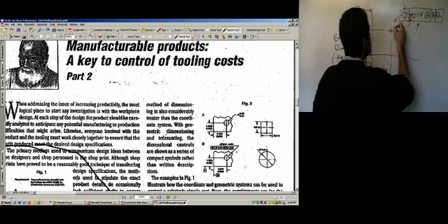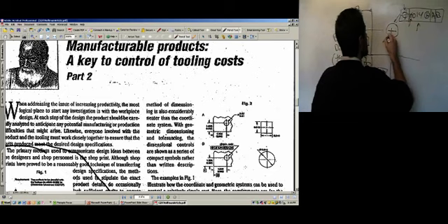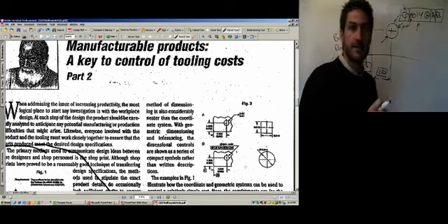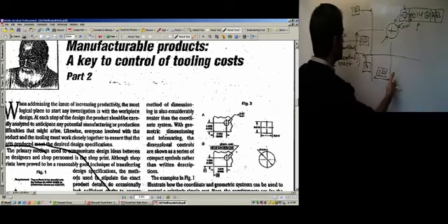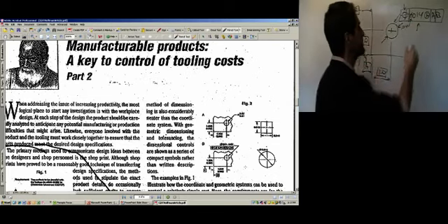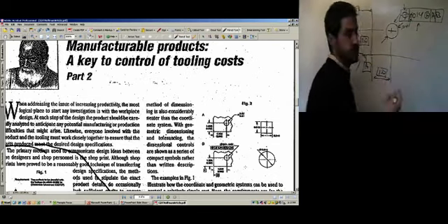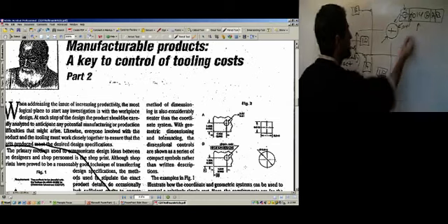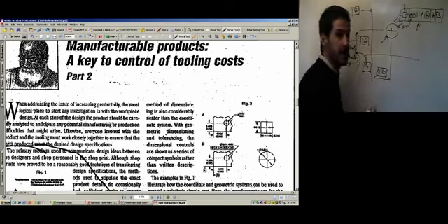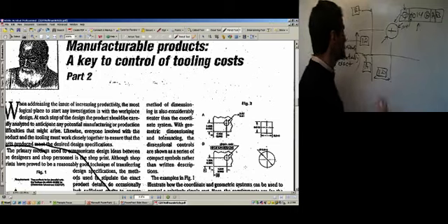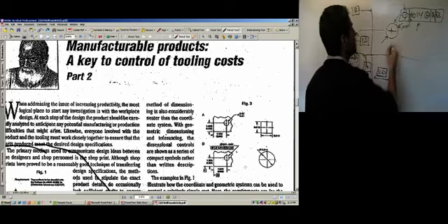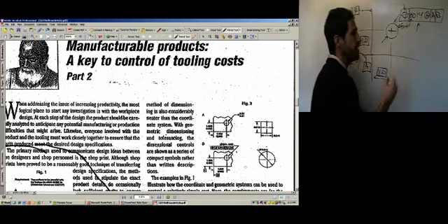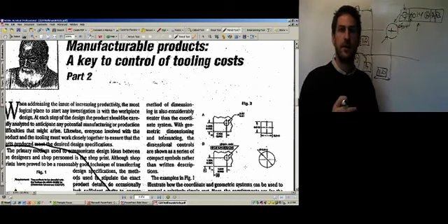It's 0.014, and the center axis of the hole has got to fit in there with respect to A and B, meaning it's 1 inch over from B and 1 inch up from A. That's what the A and B means with reference to those surfaces. But we come back to the basic dimensions here to see exactly where it's supposed to be centered. Those basic dimensions tell you that the center of the tolerance zone is there, and it's 0.014 in diameter. Now that makes more sense, a circular tolerance zone.